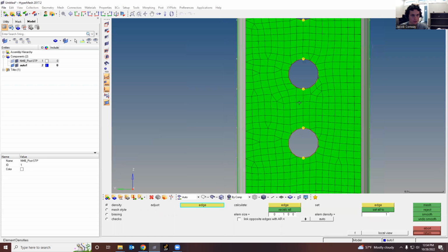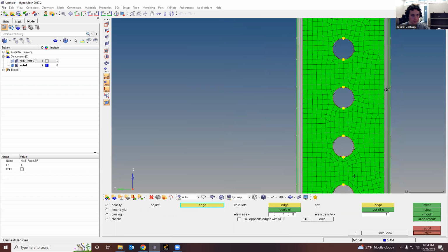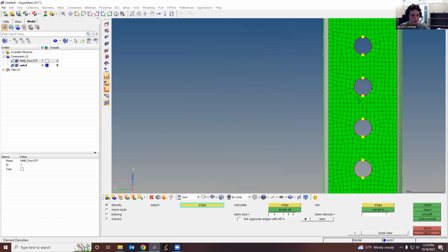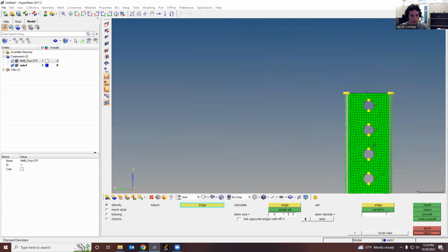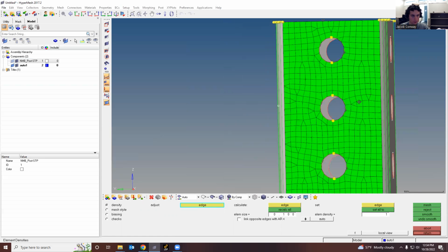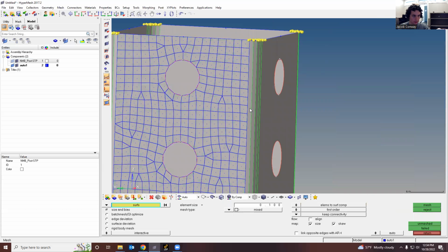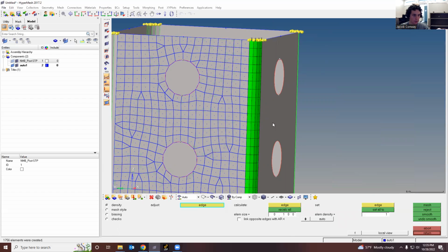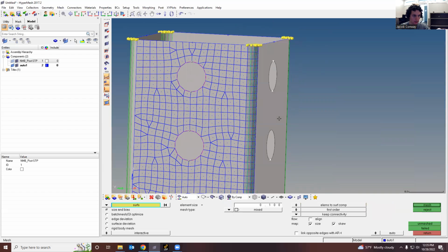Yeah, this isn't half bad, but you're getting a lot of triangles. But you get some odd places, and generally it's just not great, along the face here. And you can also do these edges. We can just pretend that we want this. Click these edges too. So we're using basically the minimum size, and we're still getting kind of funky meshing to it.